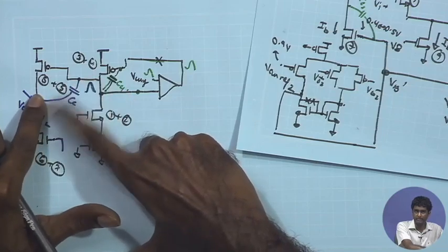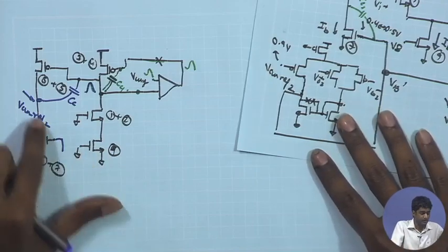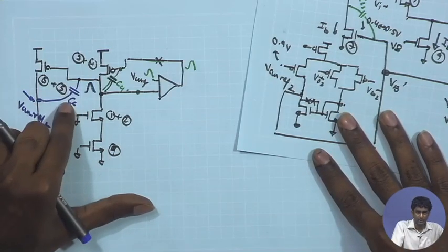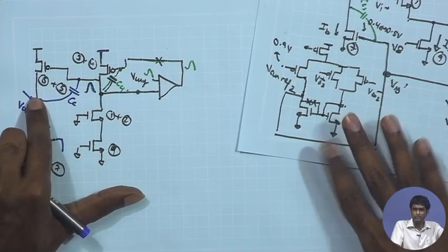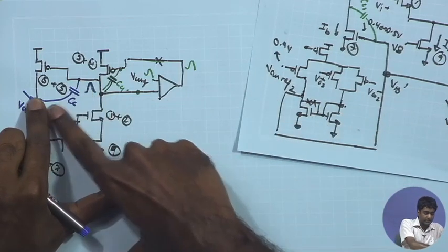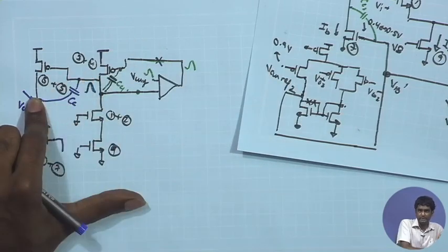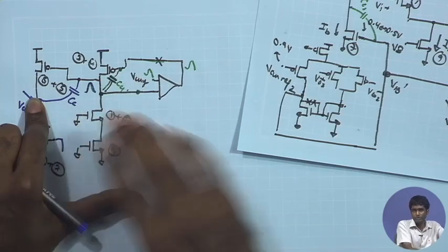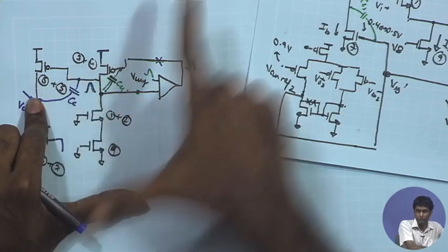Therefore, that multiplication factor for the CC is not going to come. So, we can assume that the effective capacitance coming over here will be just CC, because this is remaining constant, therefore AC ground. So, whatever capacitance CC you put for compensation of the differential loop, it will appear as if it is between this point and AC ground. So, that is not achieving a Miller multiplication which is going to disturb or push back this pole also towards low frequency.